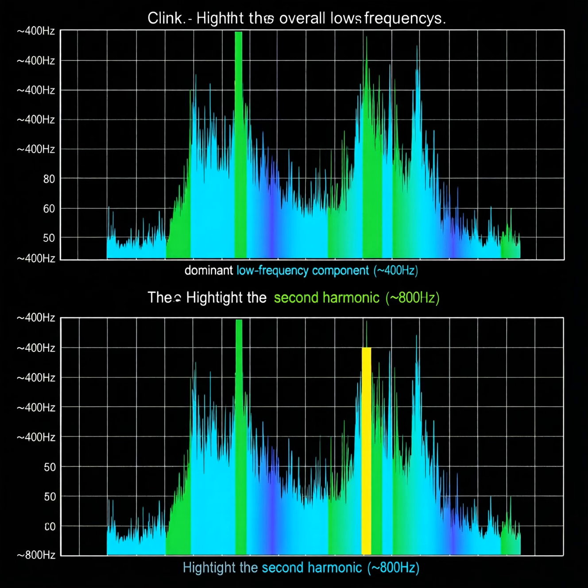These vibrations are mechanical waves whose amplitude is small but whose frequency content can be captured by a microphone positioned just above the surface. When we perform a Fourier transform on the recorded signal, the result appears as a spectrogram that displays intensity versus time and frequency. In the case of a clink, two prominent peaks emerge near 400 Hz and 800 Hz, indicating strong harmonic components.